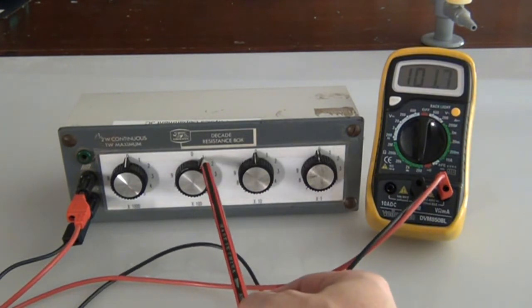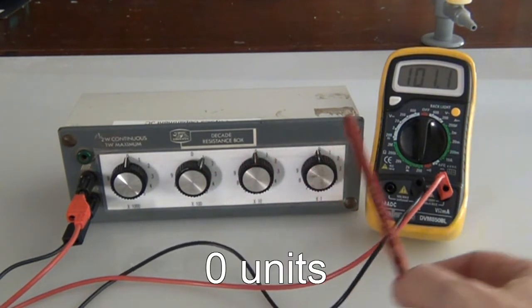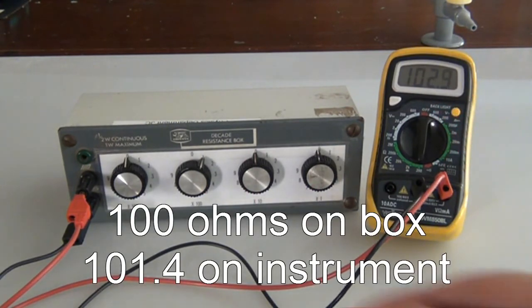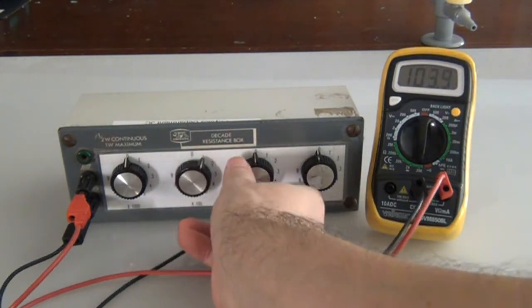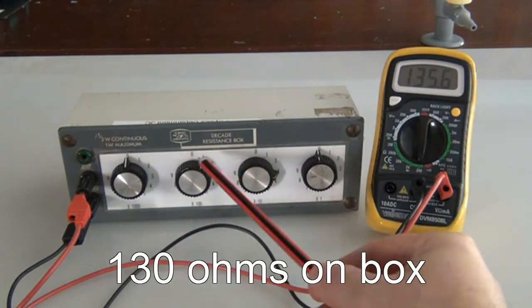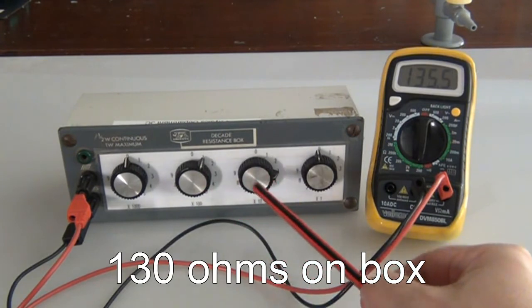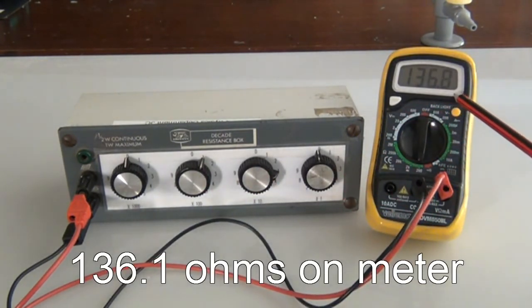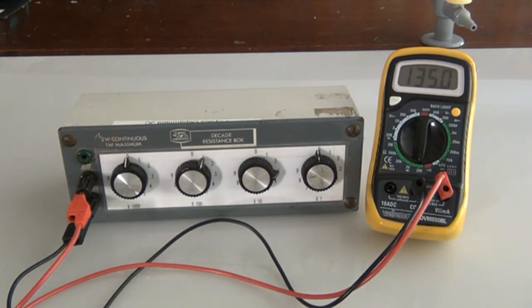We have 100, 0 tens and 0 units, so it's 100 ohms, but the instrument is reading 101.4 ohms. We change the value of the resistance and we have 130 ohms on the box, but we can read 136.1 ohms on the meter. We have selected the range on resistance.